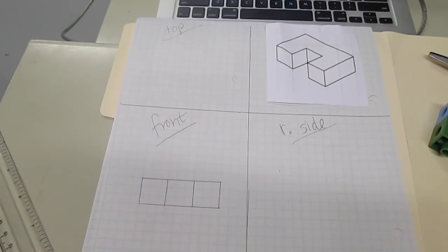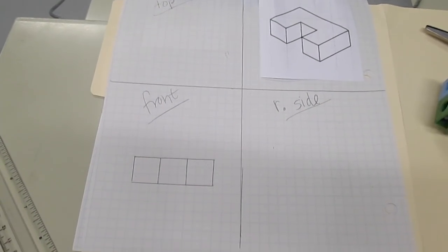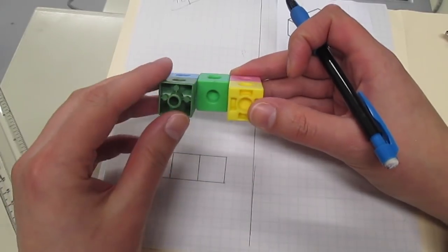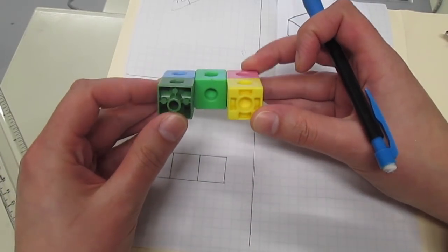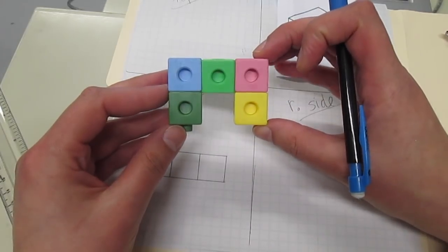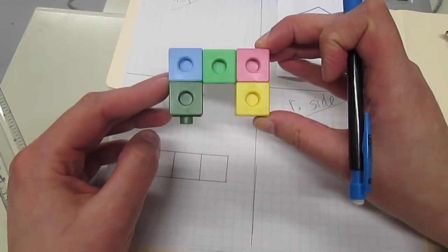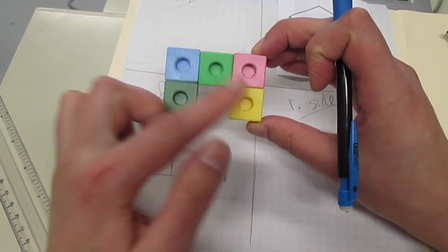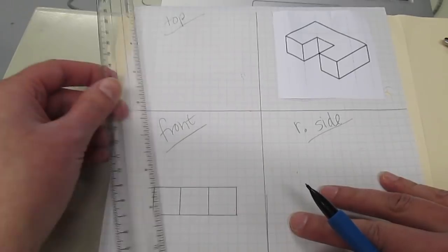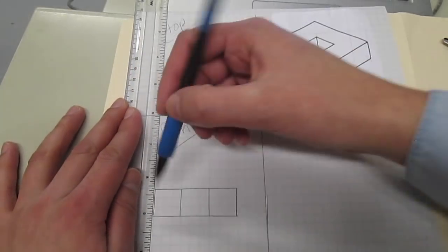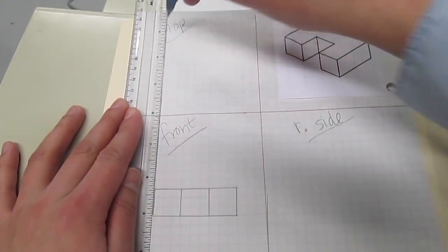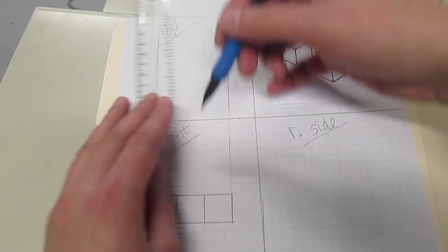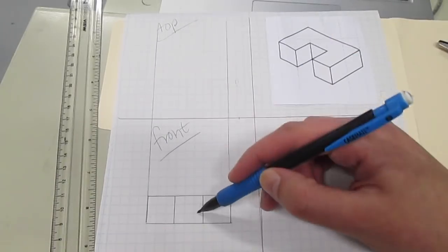So the solid lines show edge lines for lines or edges that are visible. You'll need to be in the front view in order to see the top view. So you go from front to top view, and it looks like an upside down U. I'll use some light lines or dotted lines to make sure everything lines up. Your top view should always